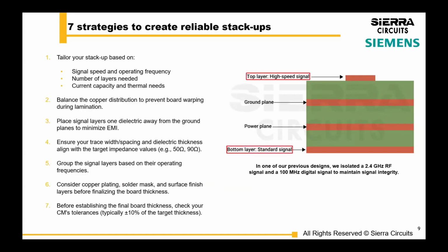For just overall strategies, really understand copper distribution on each layer. That always has to go into our DFM as well, like understanding what the layer is and understanding, do we have enough copper to really have good adhesion during lamination and good even etching. And of course, every design is unique, so that's where the feedback from the fabricator comes in.